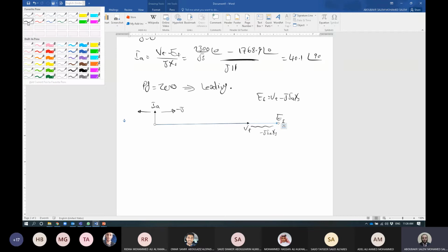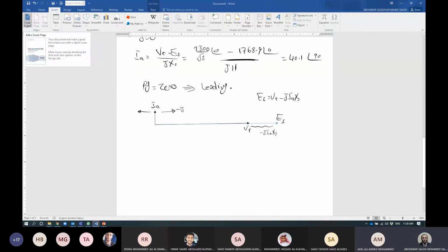Who thought about it and can tell us? Yes, I think that when the power factor is unity. Who was first? Who is speaking with me? Adel. Okay, Adel, please go ahead. When the power factor is unity and there are no losses and no load, the current has to be 0. Exactly. This is very good.